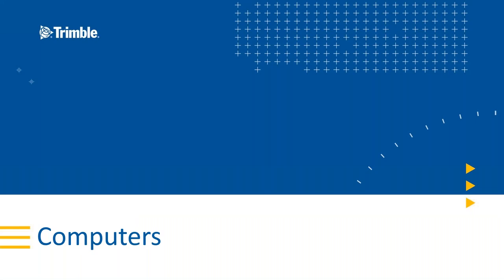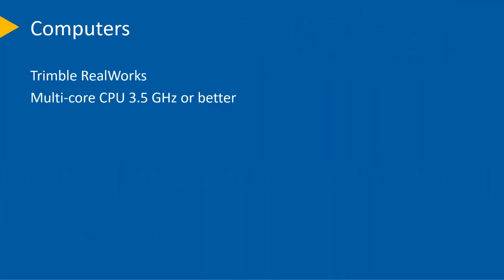Now, that's the software. The computers that it takes to run the software can vary as much as the software itself. But generally, when you look at computers, I'll give you an example for Trimble RealWorks. I'll look for a multi-core CPU, probably 3.5 gigahertz or better. The faster the processor, the faster you can crunch your data. Now, a lot of software has some multi-core support. Some don't have any. But it does help in various places. For example, in Trimble RealWorks, when I'm importing, registering, and converting scans, having multi-core CPUs makes this run significantly faster in that it can assign a scan to each thread.